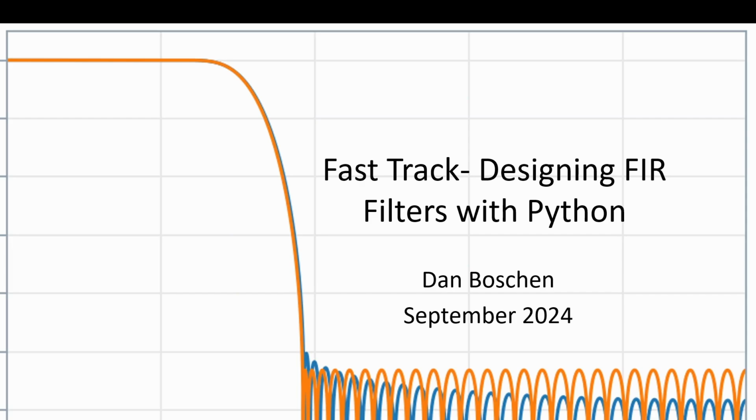But the common theme was always SNR, optimizing signal-to-noise ratio. How do you deal with all the different types of noises? I'd be the one to ask, like, what's the optimum control loop or tracking bandwidth for a carrier recovery loop, for example, or what's the noise figure of a FIR filter? Put it that way, in terms of working on both the analog and digital side, so more of a system perspective on these things.